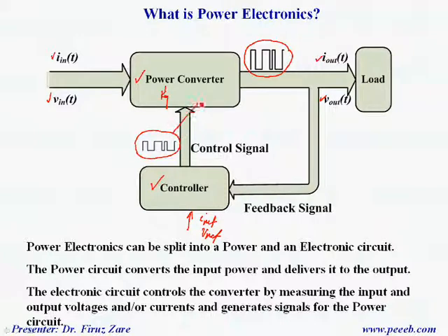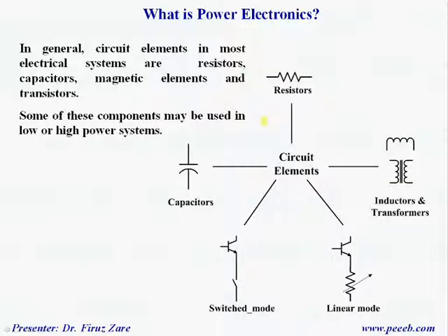That means power processing means a mapping from low voltage into high voltage. That means using signal processing we can synthesize any voltage or current waveform, and then we can generate the same signal in high voltage, high current.